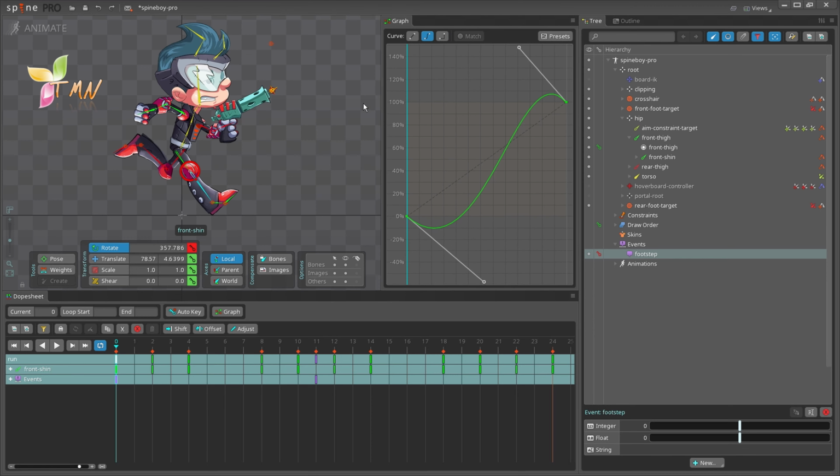When multiple keys are selected, the first selected key is drawn as normal and can be changed, but the other keys are drawn in gray. When match is enabled, modifying the curve type or moving the Bézier curve handles will modify all the selected keys to match the first selected key.